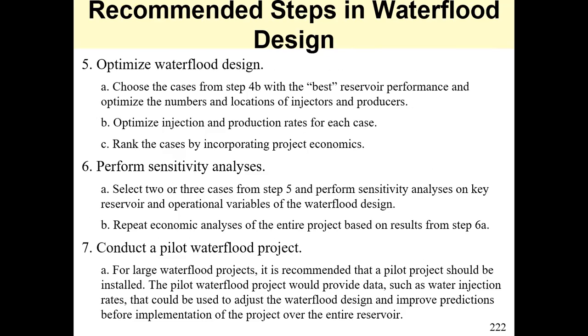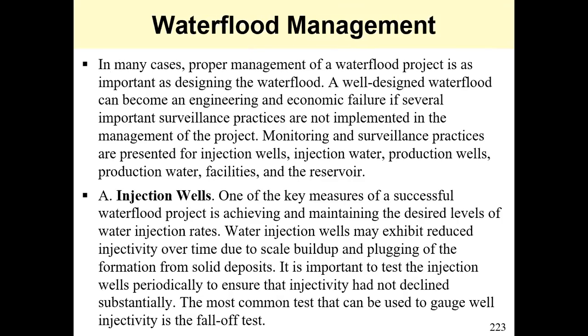So all this is done using the simulator prior to pilot projects, so that you can look at different water flooding patterns, even those that are irregular, and see whichever one optimizes your injection and production rates. And then you also look at the economics. It's after you've done all that, done sensitivity studies, that you go ahead to conduct pilot projects.